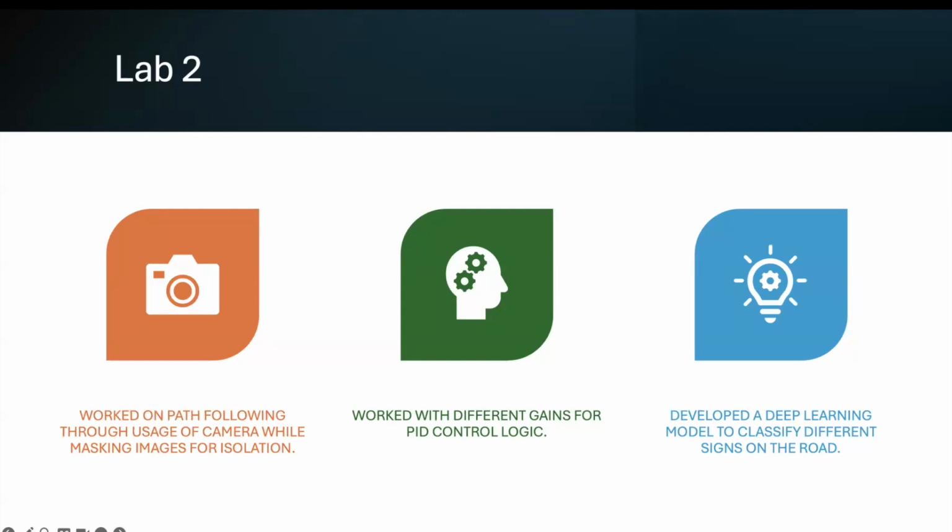So first, by separating these different images, we label them, go through all of it, go through different epochs, and in this case, the robot, through different decision trees as well as neural networks, will be able to find the best algorithm to recognize what it was shown, whether it was a stop sign, a speed limit sign, or just nothing at all. In the end, the way we calculate which one it was is that with a confidence probability of more than 0.85, you'll be able to determine whether it was one of these three.